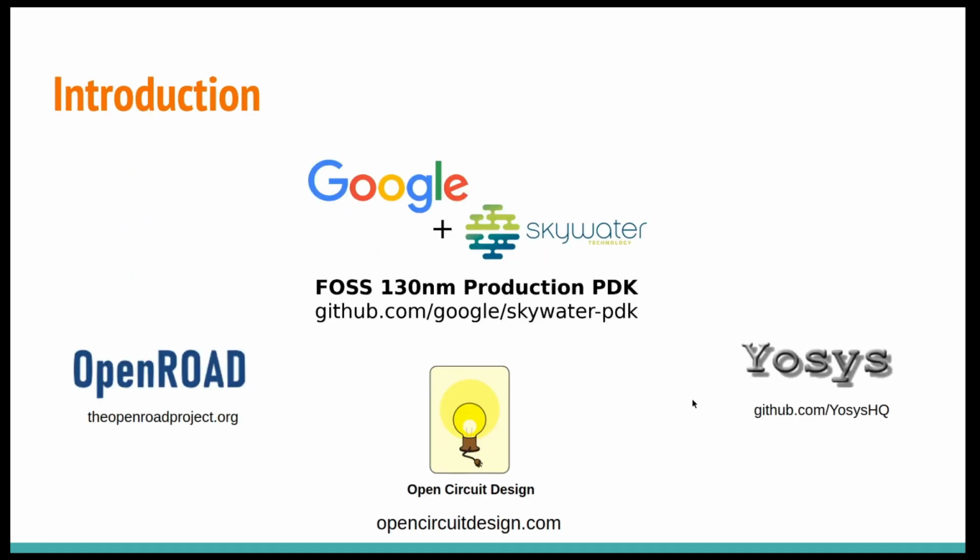So the OpenLANE project started at the intersection of several unprecedented open source efforts, most notably the then ongoing work to open source a manufacturing ready PDK, and the ever maturing EDA tools from logic synthesis to placement and routing to physical verification and so on. These tools, which are mainly developed by OpenROAD and Open Circuit Design, are also augmented by a number of other custom tools and scripts that extend their functionalities. And the way all of these tools are used defines the methodology of the flow.